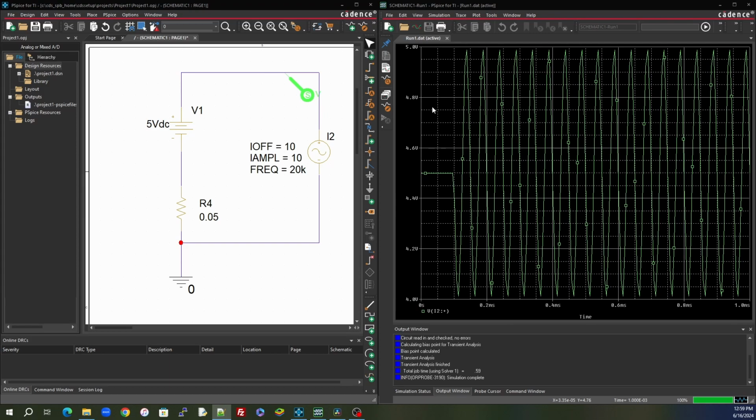So the problem with this one is that the voltage gets all the way down to 4 volts. I'm just going to throw this out there for the sake of the video: what we want on our output is to make sure that we stay above 4.5 volts, because we've got some IC on there with a minimum operating voltage of 4.5 volts.